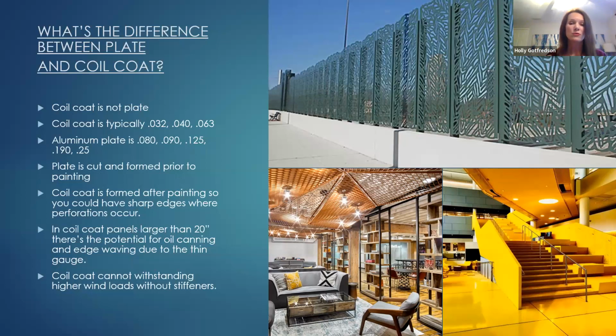Think about, especially in a school application, a healthcare application, if you're doing perforations through coil coat, you're going to have a raw edge that's going to be exposed in those perforations. And that could lead to people getting cut if they're running their hands. If you're using those perforated panels as like an infill panel for a stairwell, kids could cut their hands, all kinds of different things. And if they're outside, then that creates an opening for oxidation and rust to occur pretty much immediately. So post-fabrication finishing perforated products is really key for longevity and for strength, for resiliency, and also for safety.